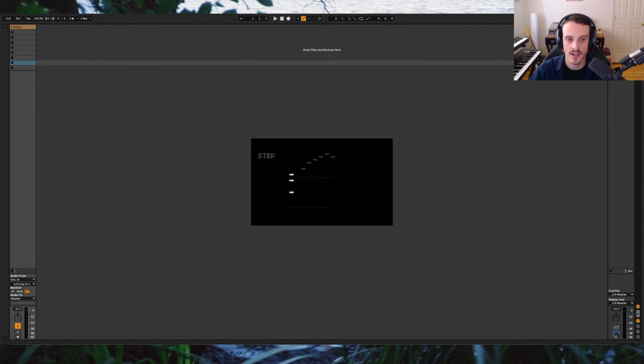This page allows you to change the note output of each step. Encoder 2 moves between the different steps of the sequence, and encoder 3 will adjust the pitch. Pressing button 3 will morph the sequence. Holding button 1 will bring up the probability control. This determines the probability a note will sound in percent and can be adjusted with encoder 2. While continuing to hold button 1, pressing button 2 will clear the sequences, and button 3 will randomize them. Pressing button 2 will swap between the two sequences, and the controls are identical between the two.